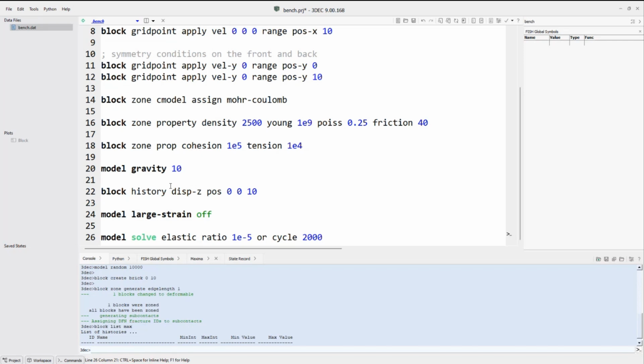So note here that we did not specify any initial stresses. So this thing is unstressed. We're turning on gravity. What you're going to see is a huge downward force acting on all the grid points because of this gravity. This instantaneous huge downward force can actually cause things to fail right off the top. It's essentially setting up a dynamic wave that propagates through the system with a fairly high amplitude. That's not realistic. Gravity doesn't just turn itself on magically. So we kind of don't care about the state during this initial equilibrium, due to gravity.